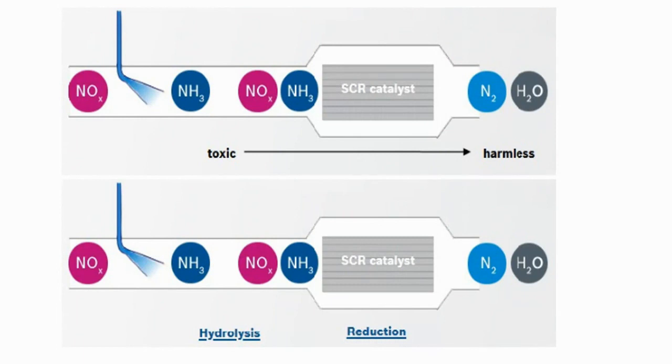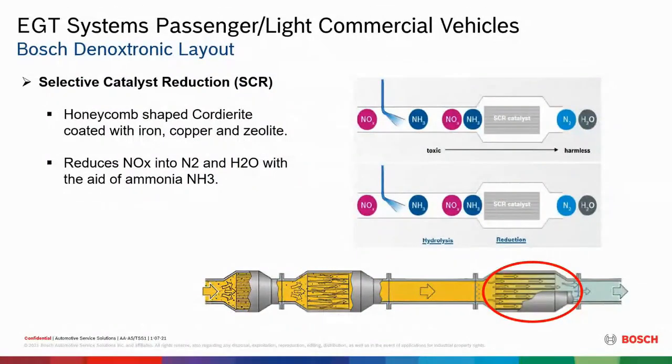We do the best job we can, but you have to realize that on and off the throttle, acceleration times, we have to map that with the dosing module in order to dose the right amount of fluid. I'm going to get into that a little deeper, but it's a challenge to hit that target exactly. So when you put your foot in it right away, you're probably going to see the NOx climb up really, really high. There's nothing you can do about it until the DEF fluid gets through the system and starts converting in the SCR. Like I said, I'll talk a little bit more about that after. But through hydrolysis, we do a reduction process in this SCR in order to lower these products down inside here.